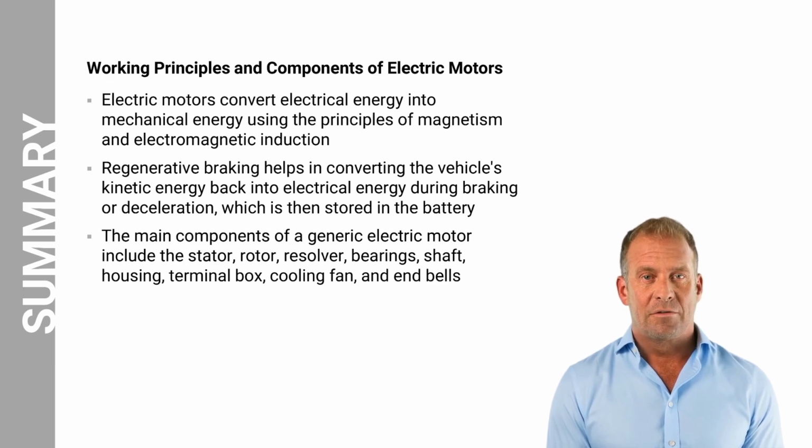Regenerative braking improves energy efficiency by converting the vehicle's kinetic energy back into electrical energy during braking or deceleration, which is then stored in the battery. The main components of a generic electric motor include the stator windings, rotor, resolver, bearings, shaft, housing, terminal box, cooling fan, and end bells, each serving a specific function in the motor's operation.